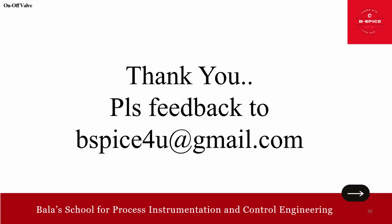Just as a recap, what we have covered is general information, line data, process condition. The main part is the body and trim we covered, actuator also we covered, air set, performance also we covered, position switch, solenoid valve also covered. And finally, we touched upon a bit on the options and accessories.